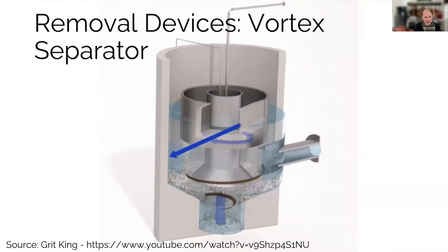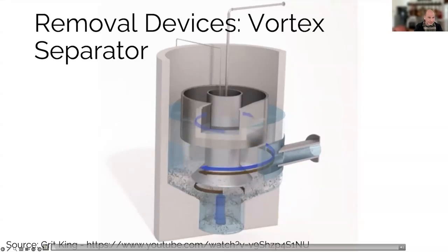And they're typically proprietary. Like I said, there's some companies that make these, and you'll have to get maintenance and spare parts and things like that directly from them. And ideally, you would want to have 2 grit channels, you want to have redundancy with these as well so that you can deal with repairs or unexpected high flows at a small plant. But typically small plants aren't going to be able to afford these because they're quite expensive.